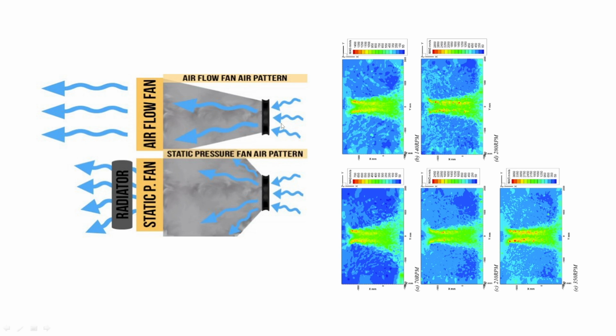So if you're using these fans on a radiator that is at the front of your case, you still want to make sure you've got good strong airflow, especially if your GPU is air cooled. If everything is water cooled, it doesn't matter as much. You still want good fans, but the airflow pattern of the fan doesn't necessarily matter as much, so you can just go with whatever meets your performance needs.